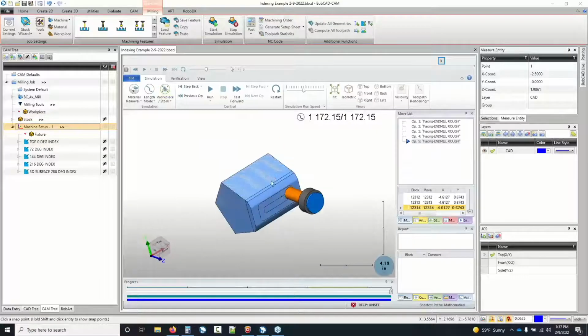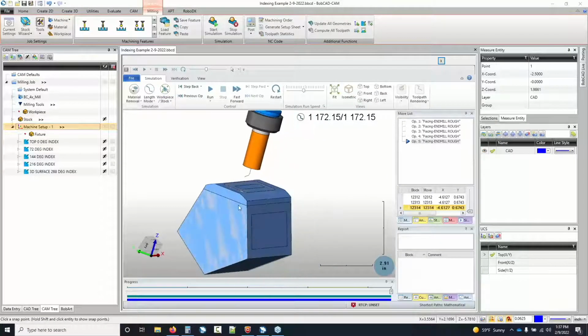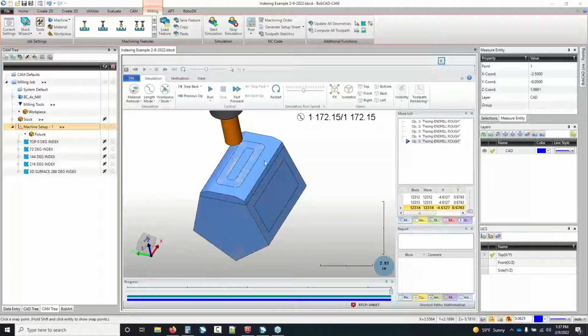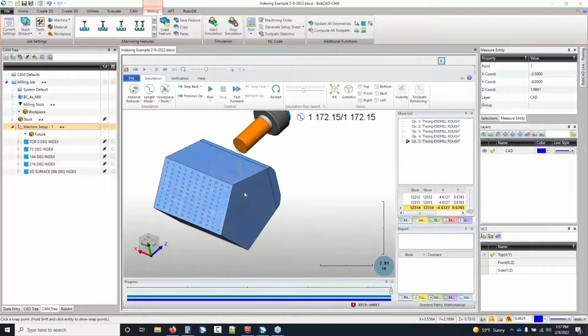I turn off the machine. I don't need to see it. Now I can see everything. So that looks pretty decent so far. We got a bit of cleaning up to do for the 3-axis, but we're going to do that with the 3-axis toolpath. So it's not a big deal. And really, for the rest of it, the 3-axis is the most difficult part. I'm going to go ahead and drill those holes. We'll do the pocket on the other side, and then we'll do the 3D.